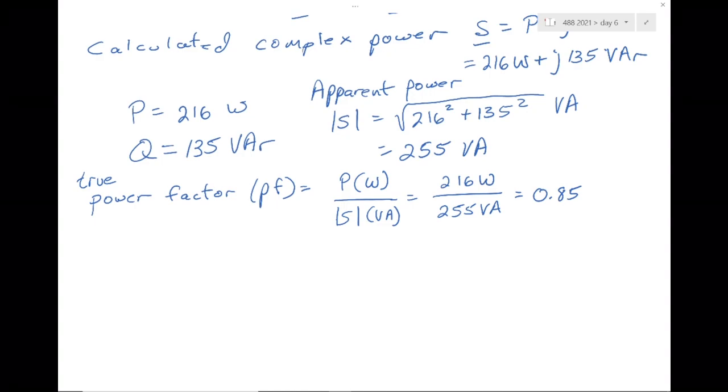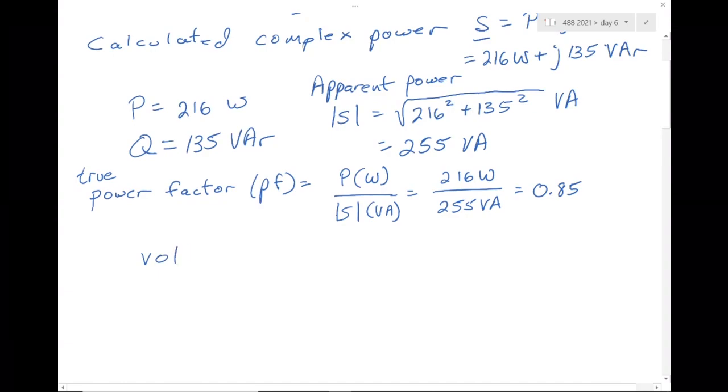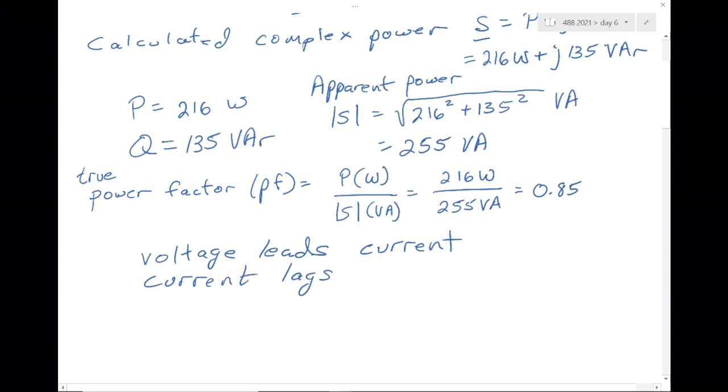So this one, we measured with an oscilloscope, and we saw that voltage leads current. In this case, current was lagging, so let's rewrite that. Current lags voltage. We measured that. We didn't have to know what the load was. Lags is the power factor. Power factor